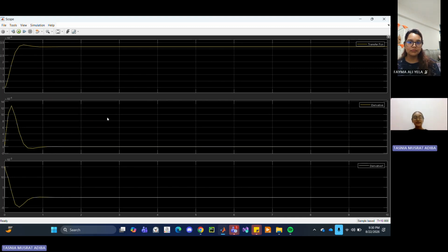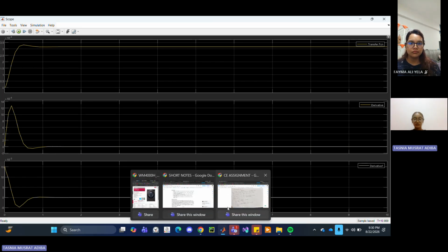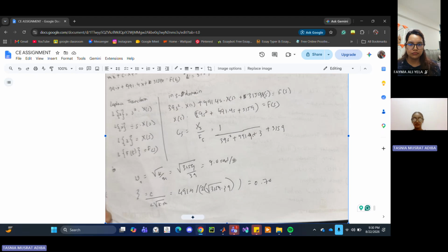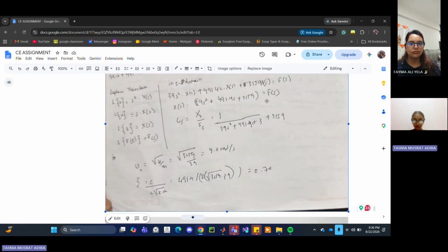And then my settling time is 1.5 seconds. So the vibration of the spin cycle can be suppressed very quickly. And it has a pretty strong frequency separation, which I mentioned in the derivation. And yeah, it's a domestic washing machine, so the specifications are pretty readily available, which is why I chose this washing machine.